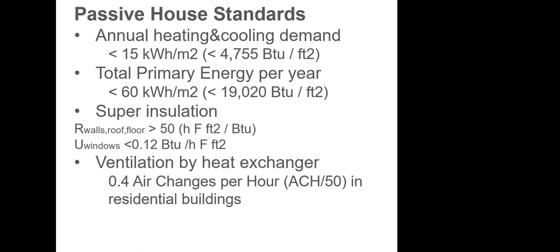triple glazing, probably argon filled, and low emissivity. Okay, triple glazing, argon filled, low emissivity. Without those requirements, we cannot have a U value below 0.12.